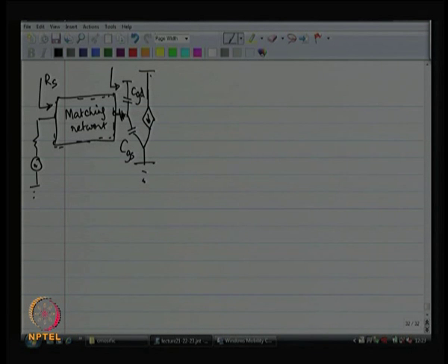What is gate resistance? It is not the resistance between gate and channel, it is the poly of the gate, it is a distributed resistor. You are applying contact somewhere and the charge has to spread all over the gate, and it has to go through a resistance to do so. Effectively you see an RC time constant. So, you get an effective lumped resistance value, that is the gate resistance. It is usually a very small resistance, who knows what its value is going to be, could be a couple of ohms.